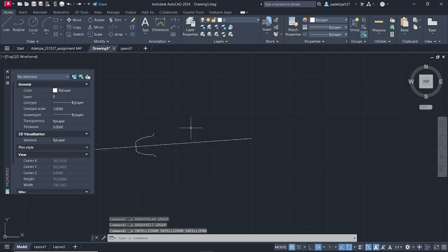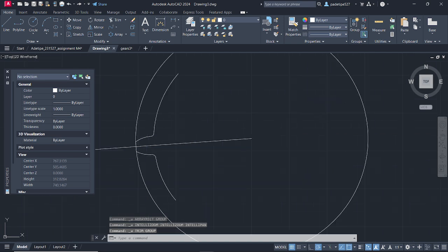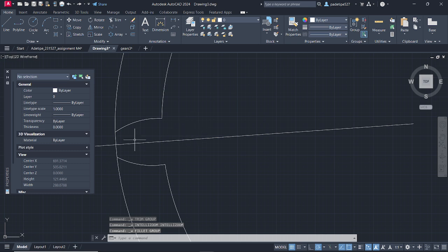Now in the filleting, instead of using that 5 points, we can use 1. Let's use 1 then. Sorry for that. So the filleting will use 1. Radius, remember radius 1. That should be the radius we want. Then multiple: 1 here, 1 here, 1 here, 1 here.